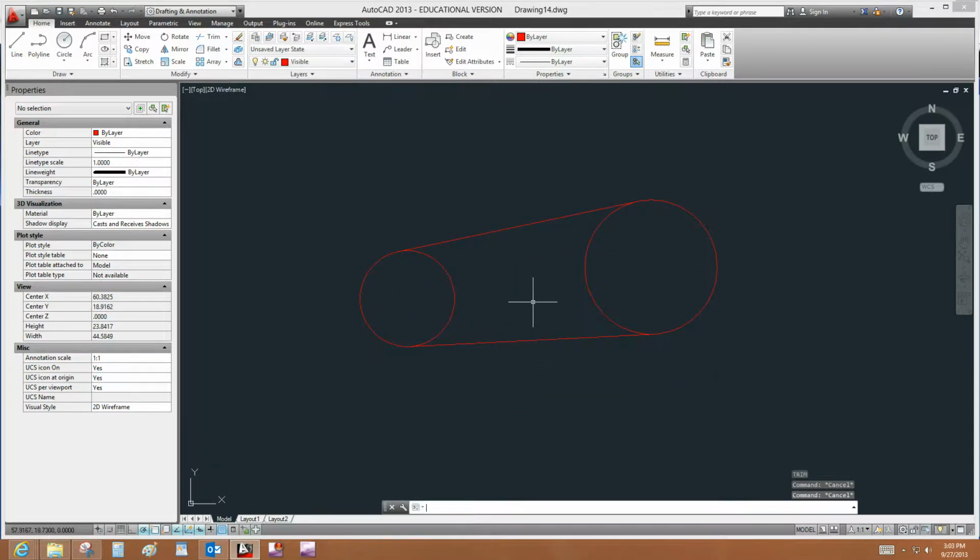Let me slow down the TR, enter, enter, just in case you missed this on a previous video. TR, enter. When I do it one time, I see select all in brackets. So if I press enter again, hence the TR, enter, enter, it selects all edges as cutting edges, okay? So that's what allows me to just click here and here, and the part that I want to go away goes away.